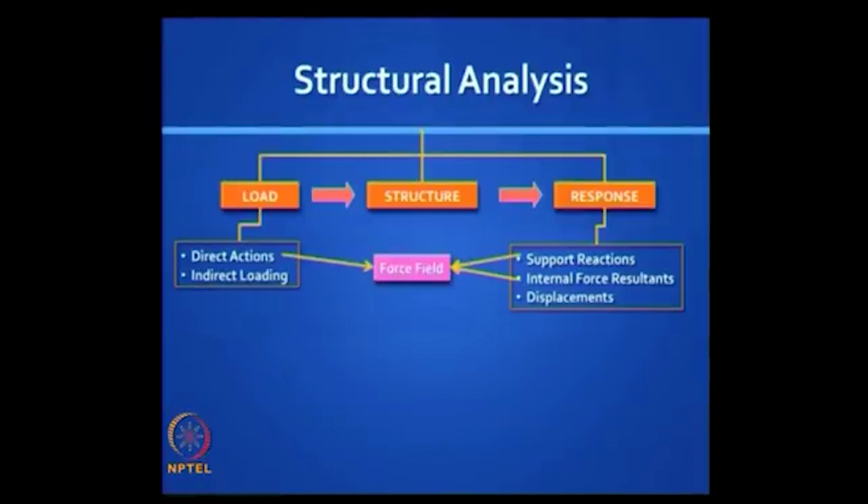And the direct actions and the internal forces and support reactions put together make up the force field. The internal forces in a skeletal structure are made up of axial forces, bending moments, shear forces, and they could vary from point to point along the length of every element.